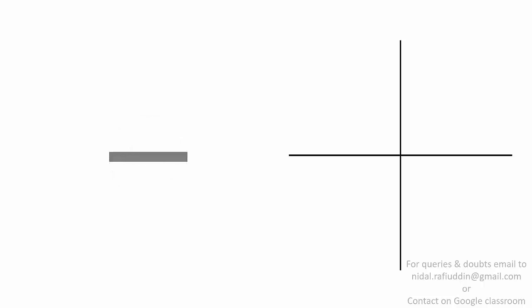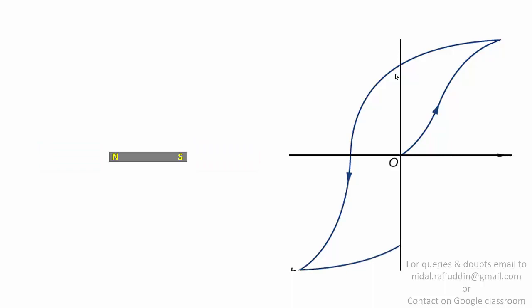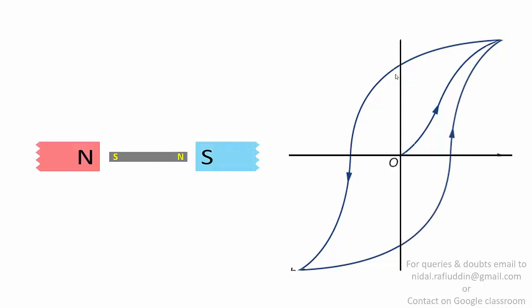If you recall the experiment for obtaining the hysteresis loop, here instead of winding a coil around the specimen for providing magnetic field intensity, we have shown external permanent magnets. Once the element is exposed to the external field, the magnetic dipoles align in one direction. When the field is removed, some of the magnetic dipoles remain aligned, making it a permanent magnet with a residual flux. A material that forms a strong magnet, such as a rare earth magnet, will have this value quite high. Now, if the external field is reversed, it causes a reversal of the magnetic dipoles of the elemental bar. Further, if the external field is now removed, the element bar gets magnetized again, but with reverse polarities as shown. Once again, when the external field is reversed, the poles of the element also reverse.